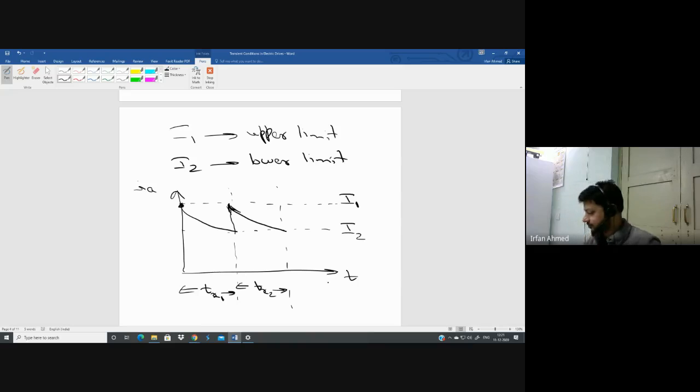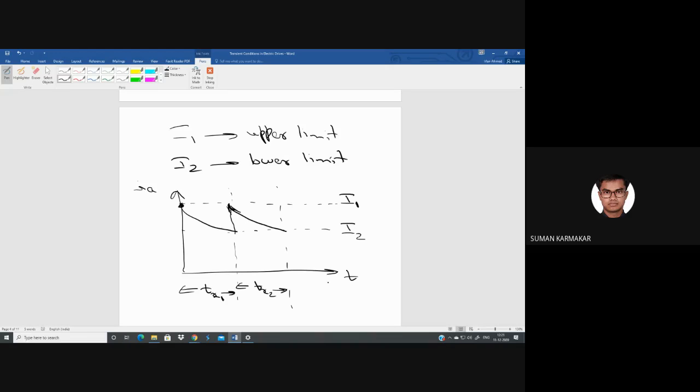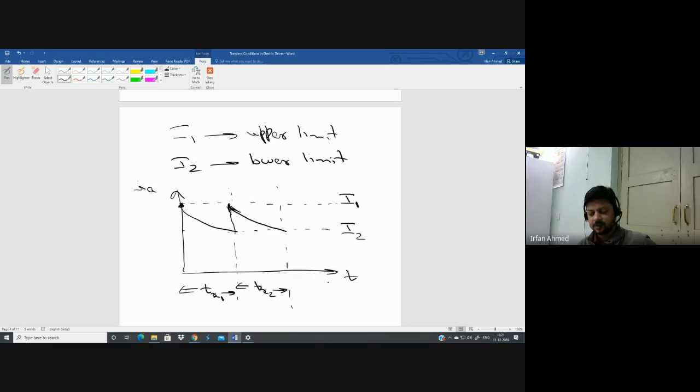So the question that I was asking was, is Tx1 equal to Tx2? Not equal to, sir. Because in case of first starting, the resistance will not be equal. Tx1 will depend on the time constant, and because the time constant in the first case is greater than the time constant in the second case, Tx1 will be greater than Tx2.